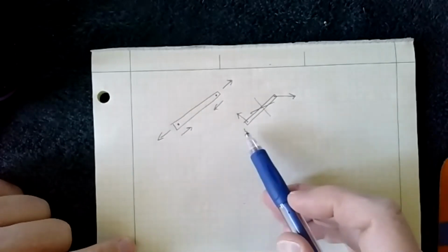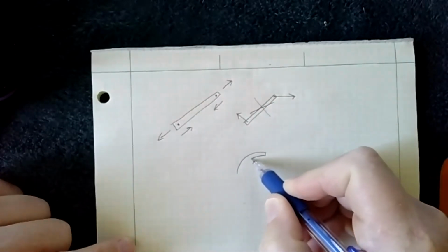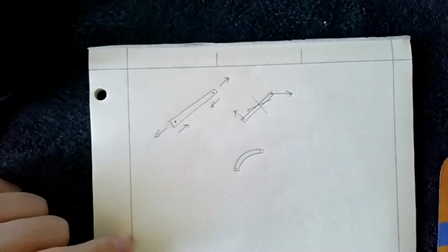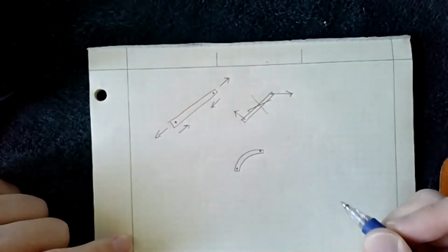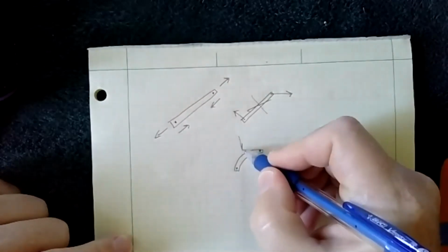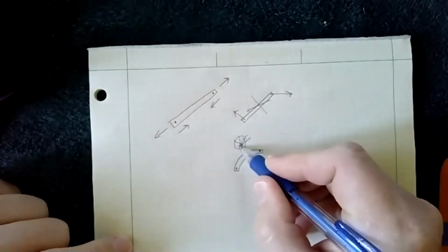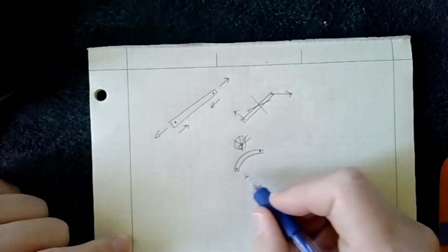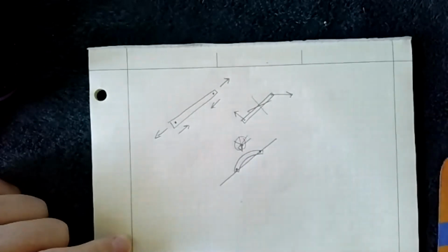Now, it doesn't just have to be linear. If we have something that's, say, a quarter circle like that, then in that case, as long as it's only pinned in two locations and there's no force applied from the outside, the direction of the force on this quarter circle would be through the lines, so through the pins.